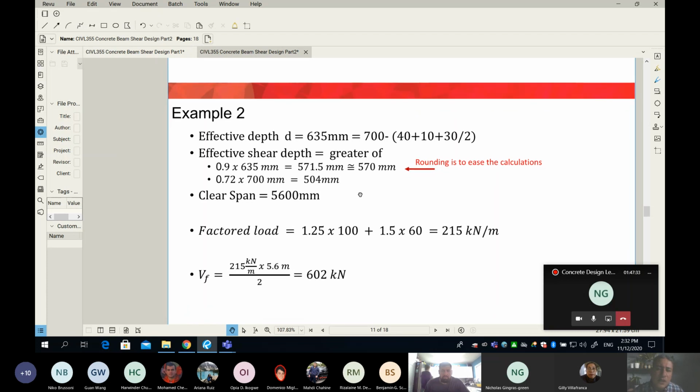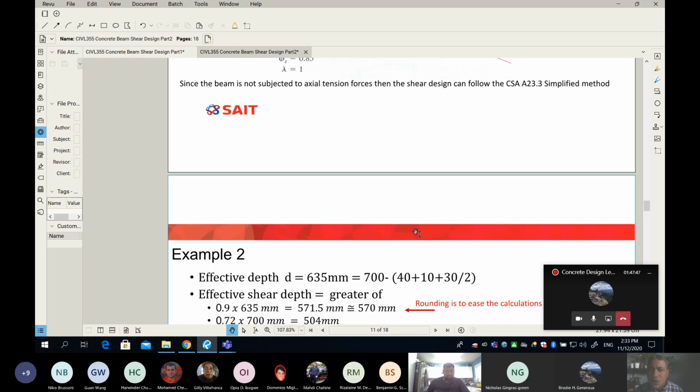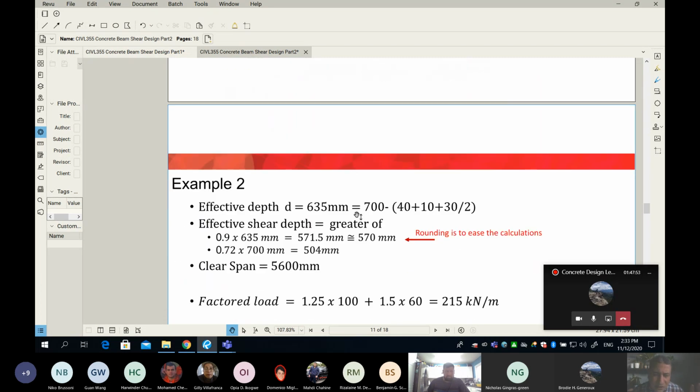Sorry, Tahir, I have a quick question just for that part. We don't need to check our minimum b value to see if we have two layers first? Well, the beam here is quite wide. Look, the beam width is 600 millimeters. The beam flexure design has already been finished, so somebody else did the check for the width. If you go ahead and do it, you will see 600 is too wide. It can very comfortably take the 4 bars of 30M.